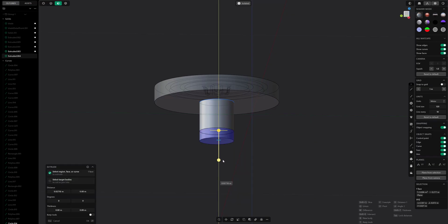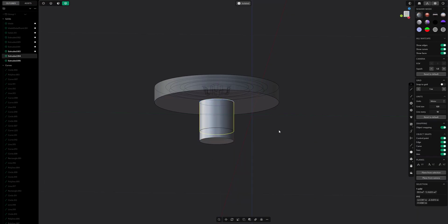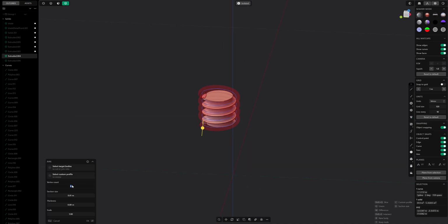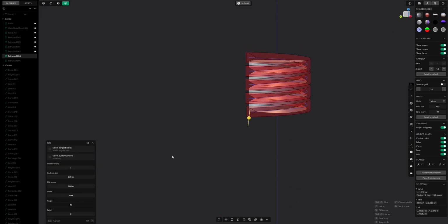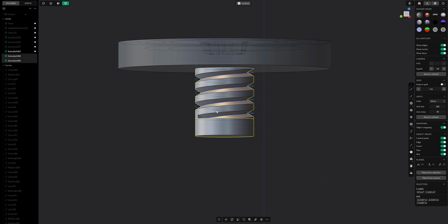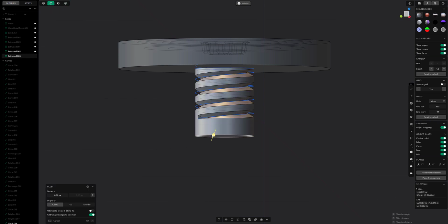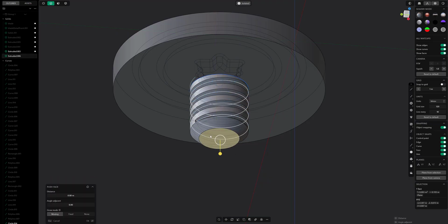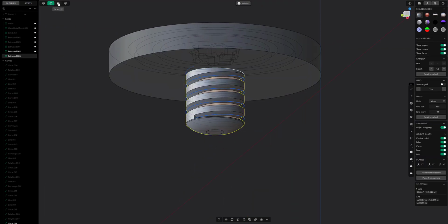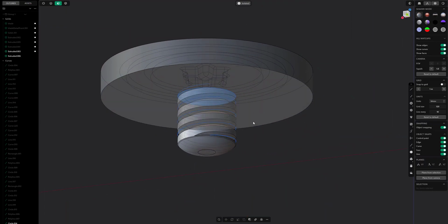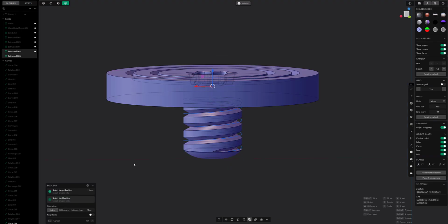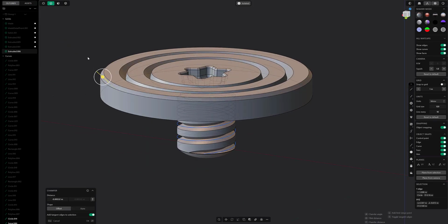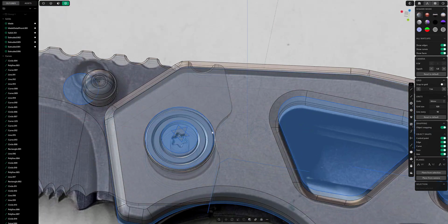But I'm going to go ahead and add a full screw. I add an additional piece for the tip of the screw, add a spiral, and then pipe the spiral at 3 at 45 degrees, which gives the thread. That additional tip allows me to bring it back and push it in and get the shape of the head of the screw that I want. Always make sure to grab that additional face at the end and just pull it through, and it'll get a really, really nice finish. Chamfer the top, so you get a nice...